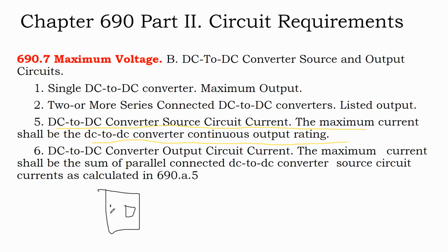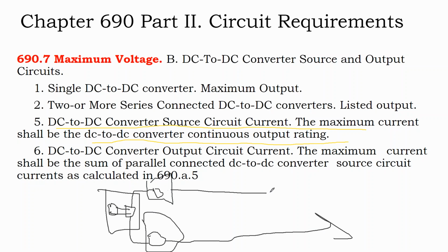So the solar leads are coming out of their own junction box and going into this optimizer, and then the optimizers are plugging into other optimizers that are on their own solar panels, and all of that circuit, you add up the output voltages of all these optimizers together to get your maximum voltage. And what we didn't do in that circumstance is correct for temperature.